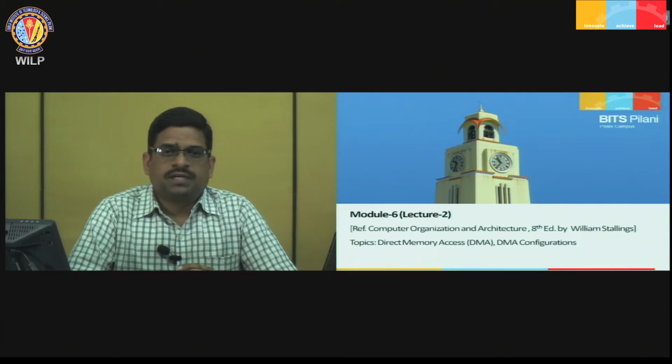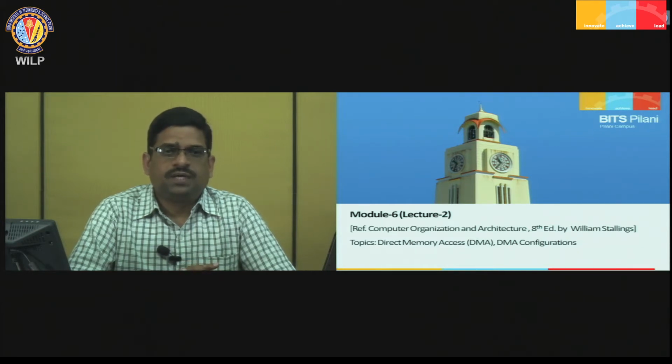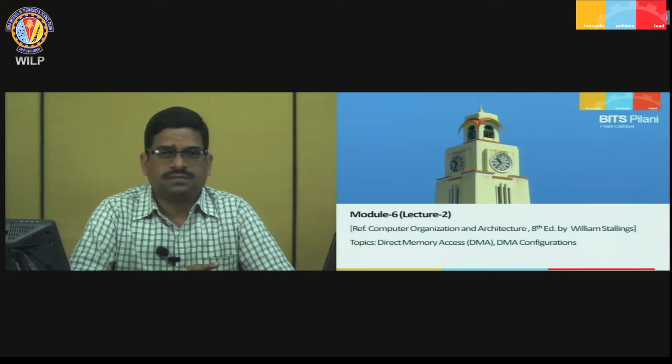In this lecture I am going to talk about the third IO technique, which is called direct memory access or DMA. I will discuss how DMA works, how it is different from the other two IO techniques, that is interrupt driven IO and programmed IO, and the various DMA configurations.